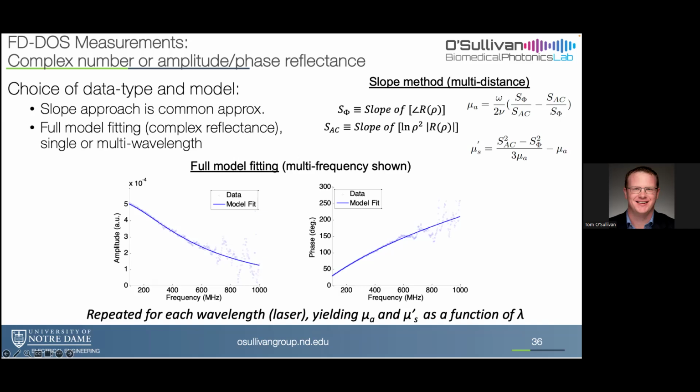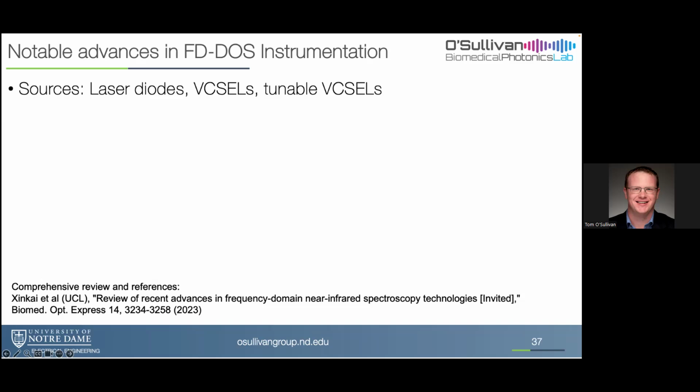Okay, so some technology. What have been some advances? Miniature laser diodes. There's a laser diode technology called VCSEL, vertical cavity surface emitting laser, that's really small. Those are chips that are like 500 micron by 500 micron. You can do really dense integration of multiple colors or put it in an implant. Detector technology followed similar to time domain, where we started with photomultiplier tubes and then moved to APDs, and our lab is really pushing the use of silicon photomultiplier detectors.